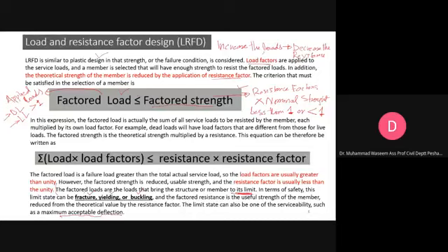So now the second distinct philosophy you guys have been using, we call it LRFD, or load and resistance factor design philosophy, okay? Now this LRFD philosophy is similar to the plastic design philosophy, okay? In LRFD you also consider the failure condition, but let me remind you that in plastic design, how do we increase the loads? How do we get the failure loads? We multiply the loads with certain load factors.